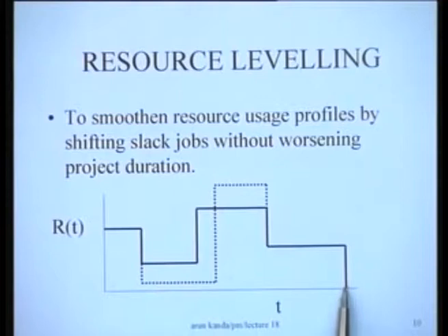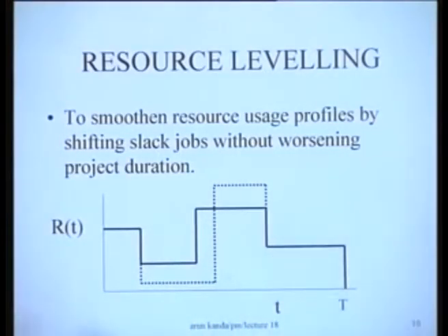Okay. So there are procedures available for resource leveling. There are both analytical procedures as well as heuristic procedures. But the difficulty with the analytical procedures is that they are capable of handling only a small number of jobs or very small projects, and for real life projects it is not possible to do resource leveling for a large project which involves hundreds of activities.